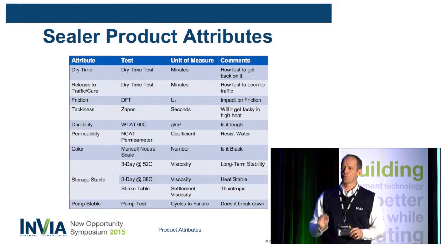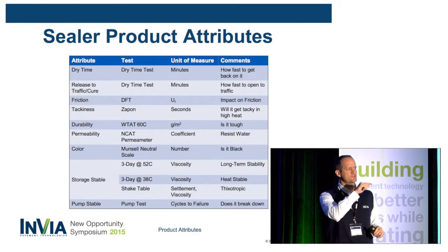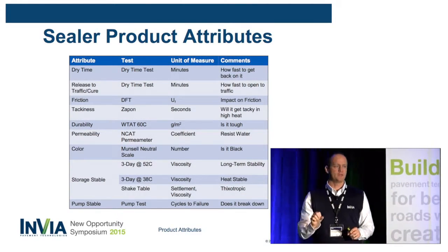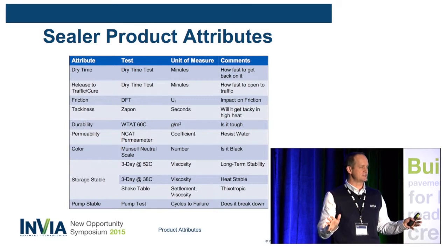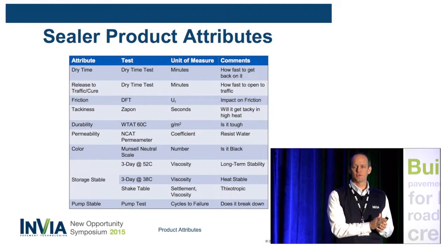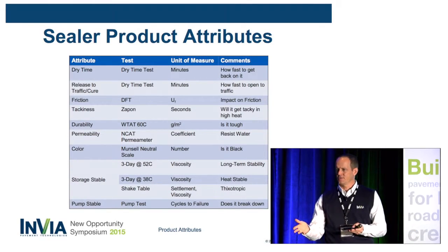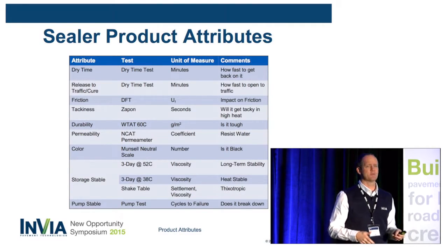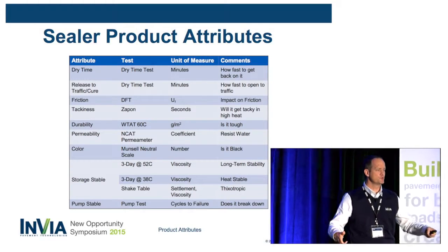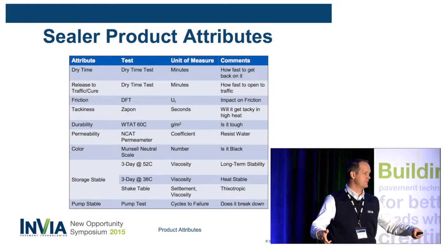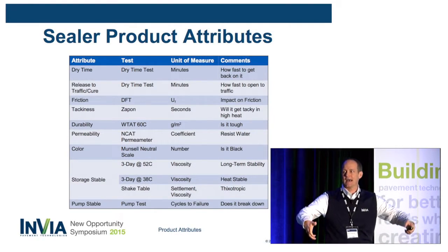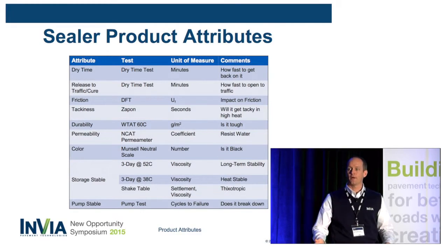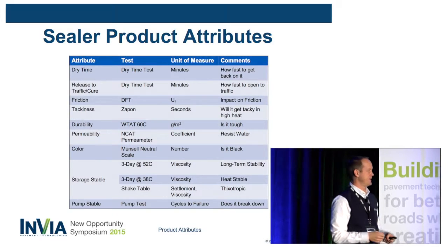And we're working, I'm not sure if we were able to get the machine down here, but we're working closely with a company called Instratech. We're in the development stages with a brand new testing machine that'll help us, rather than wearing a tar paper with our stuff on it, we're actually using slab compactors, creating a true slab of hot mix asphalt, applying our material, putting it through wear, and then testing for a lot of these attributes again.